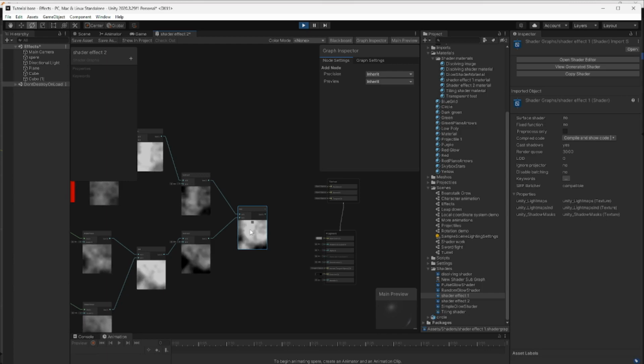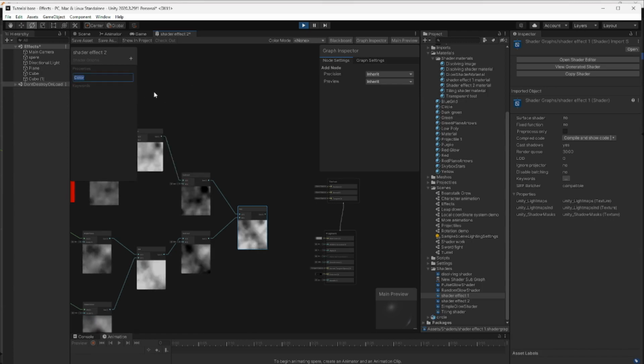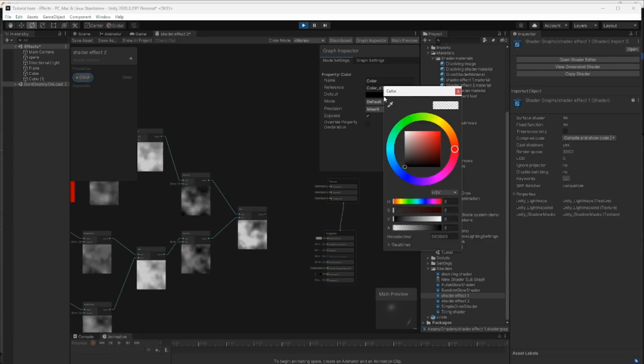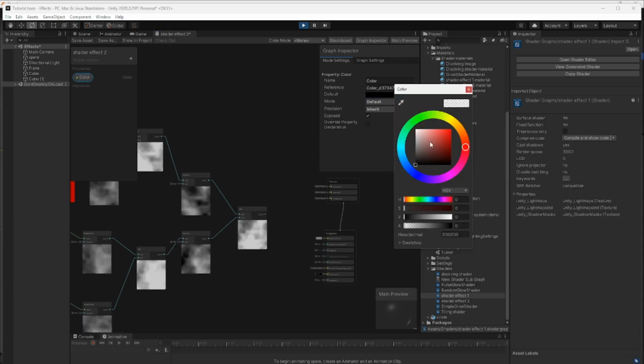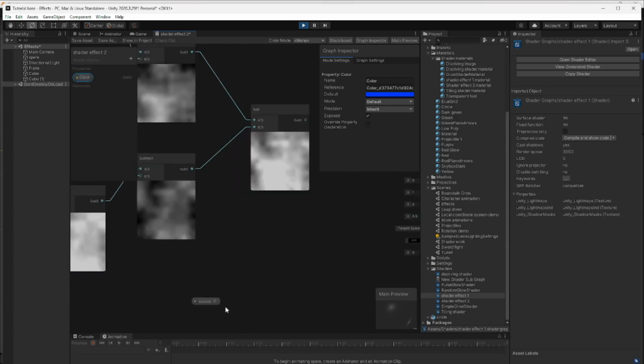And of course, this is white now, and if you'll remember from my other videos, we need to add some color. In this case, instead of just putting in a fixed color, I'm going to add an external color, which I've shown in previous videos, and I'm just going to leave it called color. We're going to mark it exposed. Let's just default it to blue. Default doesn't really matter. The mode, I'll just leave as a plain color, and I'm going to drag it down here. Let's zoom in a little bit.